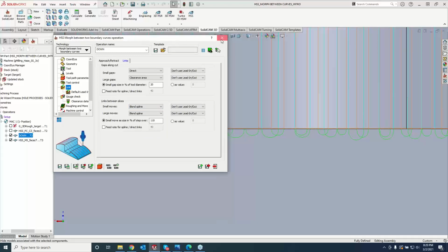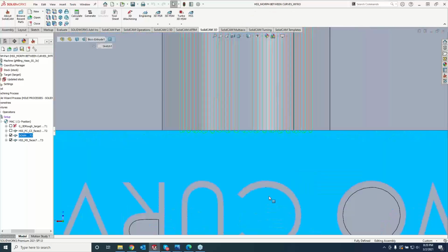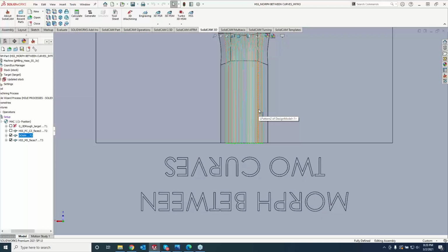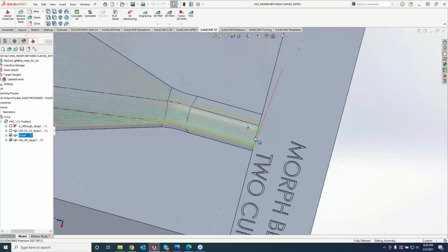There we go. And for those of you guys that don't use that, definitely try it out. Your machine will be so much smoother when it's going between those passes. Especially when we're coming in here and doing the finishing, we're going to have a little bit faster of a feed rate because we're not taking a whole lot of material off. Get that nice smooth movement going all the way through.